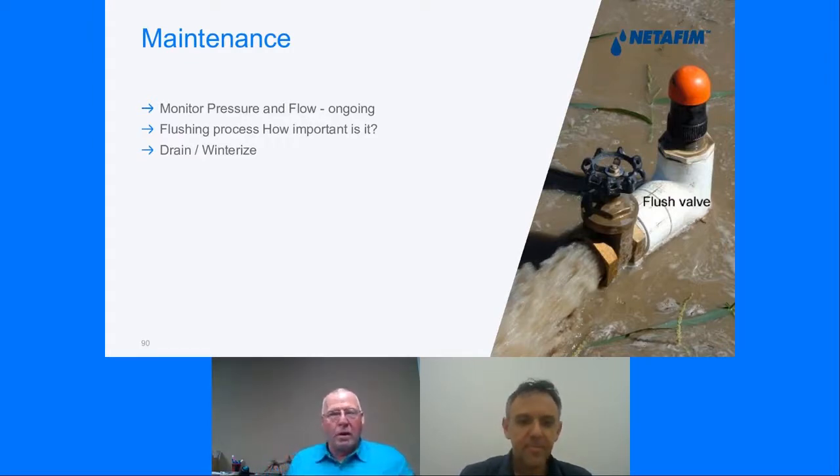That was one of the things I talked about: don't go too fast. We go from 2.5 to 3.5 miles an hour, which is about the injection speed that I prefer. I've had a few go a little faster, maybe 4. But if something happens with the injection reel, that's when you tear things up. So about 3 to 3.5 miles an hour is where we typically go most of the time. That's about 5 kilometers per hour, I guess. I hope I'm not mistaken, so do the conversion on your own.